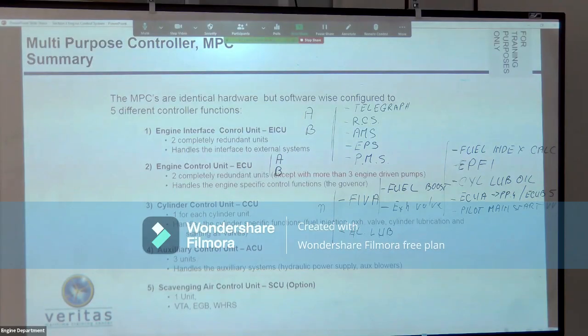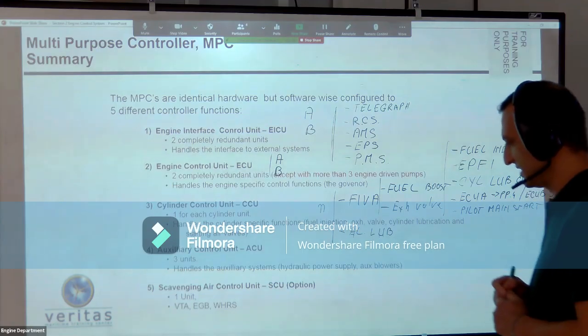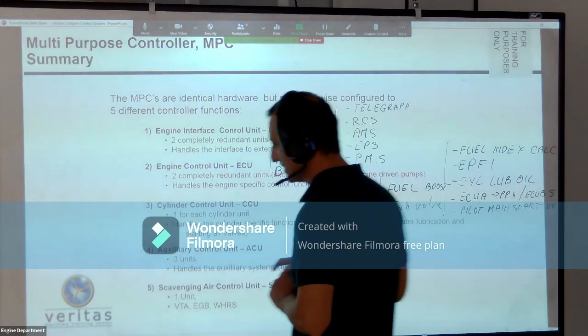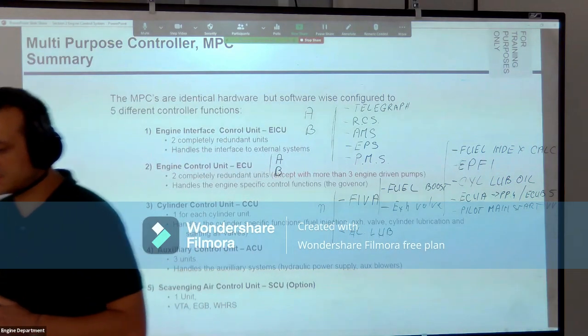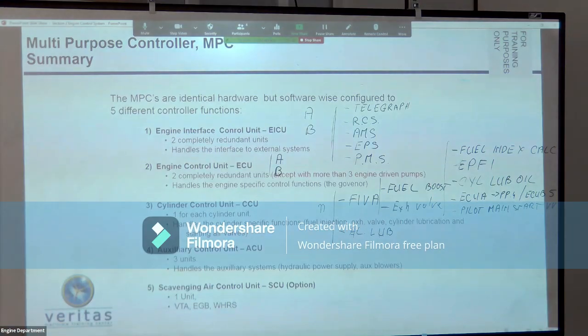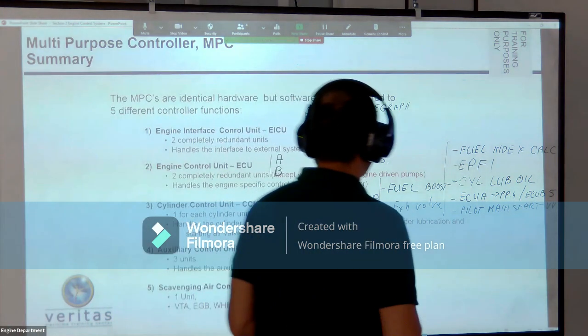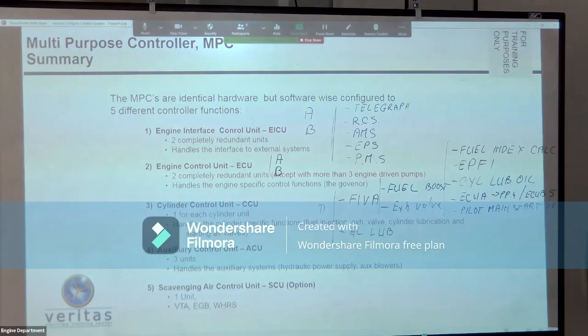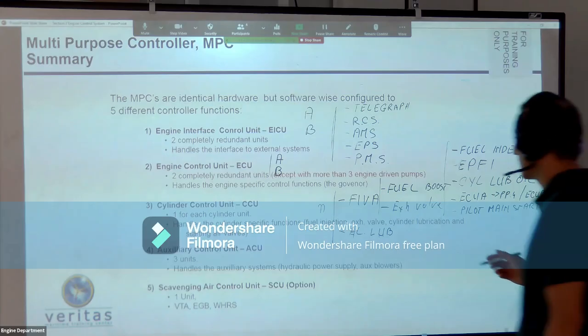And another equipment is the start pilot valve. For each starting valve, we don't have an air distributor like in the MC engine. The starting sequence is implemented in the software in the engine control system. According to the position of the crankshaft received from the encoder and the direction of rotation desired by the crew member, the pilot valve or starting valve are activated.